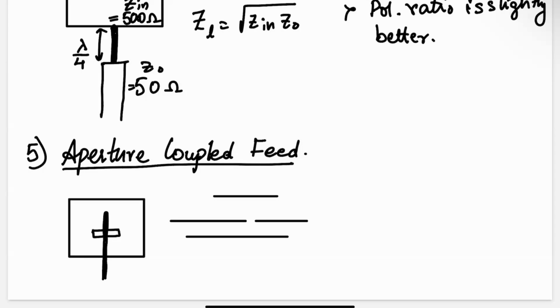Okay, so designing this is a little bit harder. There are many parameters that you need to control. How much is it going beyond that? And that adds some capacitance to this node, right? Because this is a small piece of line that's open circuited. Then this slot itself has some capacitance associated with it, and then capacitance or inductance depending on the size of the slot. And then you have your patch up here, right?